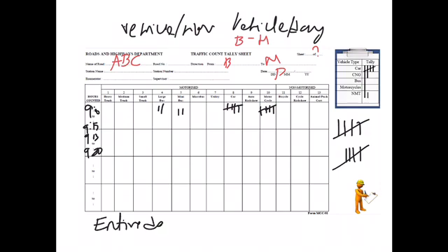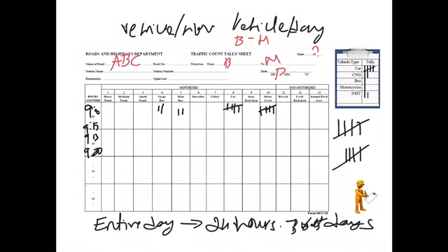Entire day details we need to collect. I mean to say that the traffic volume data has to be taken for 24 hours, covering 7 days a week, 365 days. So to have accuracy in the data you have collected, we need to collect the details throughout the year. For the entire 24 hours, data has to be available.